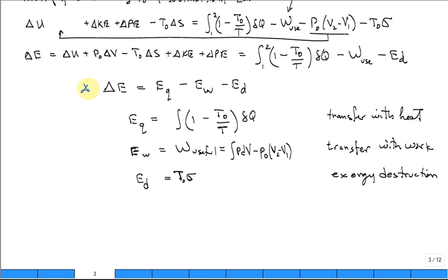True? It said, look, it's just like a first law of thermodynamics. You have a change in exergy, not energy, exergy, on the left-hand side of the equal sign. And then on the right-hand side, you have how it came in with the flow of heat, went out with the flow of work, or was destroyed. That's it. There's no mass. This is for a closed system.